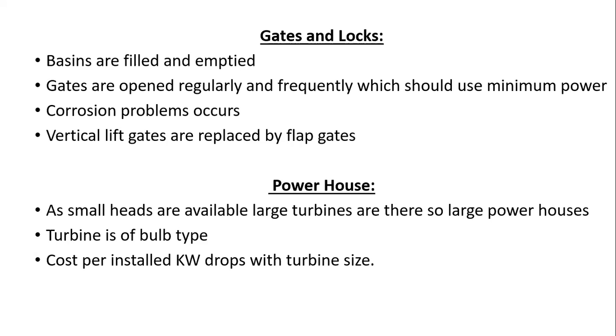Okay, if these are used, they are positioned in the case of construction in sections, where the sections of vertical lift gates are replaced by the flap gates. A section is then floated into that place. These have to be built so that they are adequate for the maximum tidal amplitude. We have to ensure the maximum tidal amplitude is covered, so that's the way they have to be designed and built.